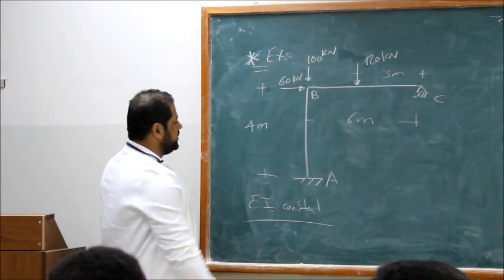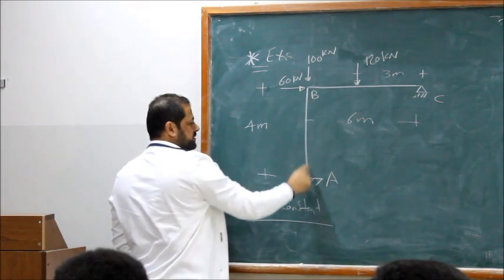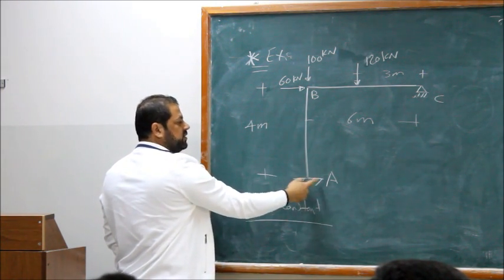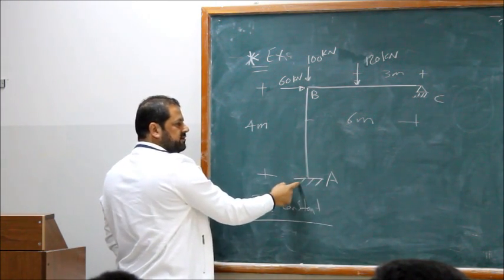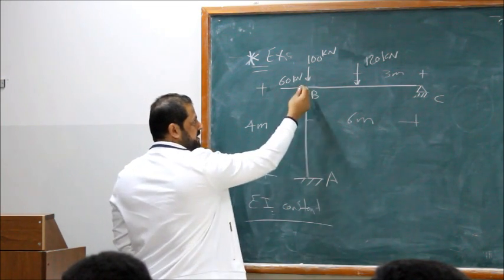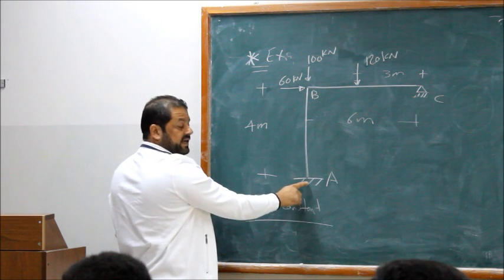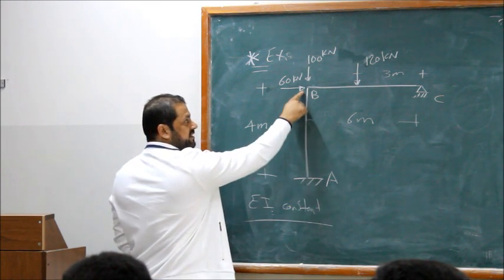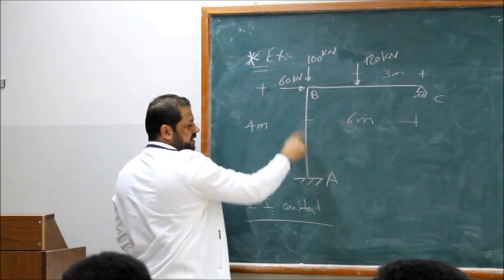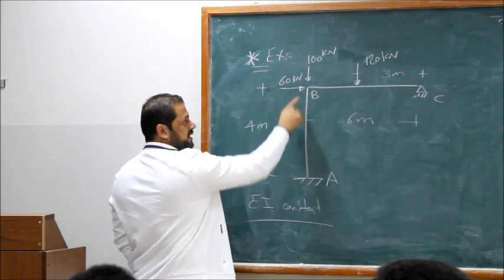Beam and girder. Look at this span. Is it an end span? End span with far end fixed. So we have two equations, MAB and MBA. Theta A is 0. We have theta B, which we don't know, so theta B is unknown. MAB is unknown, MBA is unknown.